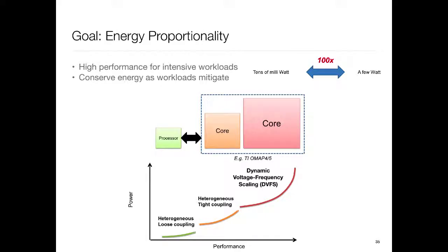And then finally, you may even have tinier processors, more loosely coupled. Perhaps this could even be of a different instruction set architecture. In ARM's big.LITTLE, the two processors have the same instruction set, so I can run my program in either place without any change, except with different performance. But maybe I can have a separate processor which is not even the same ISA.